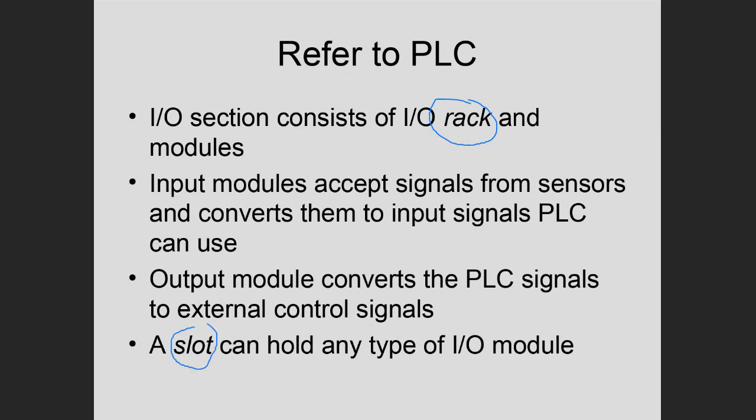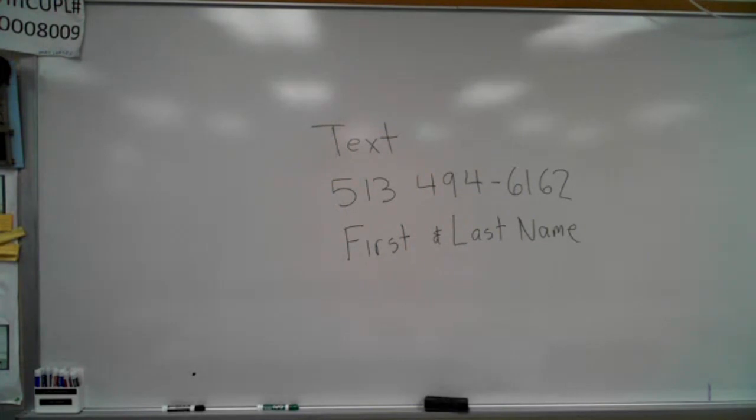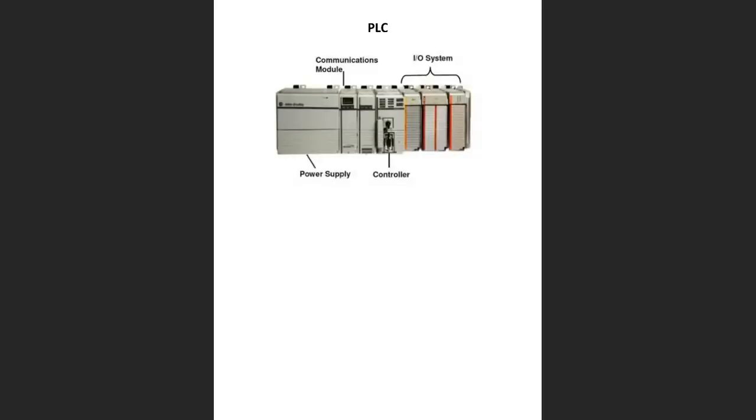Well, if you remember, we mentioned that most PLCs, the larger ones, are modular. So you can get a really small PLC, I say as small as just a little larger than a pack of cigarettes, and that's a unit where you have the power supply, the input, the output connectors all in one unit. But once you go above those small micro PLCs, then you get into the type of PLCs where you have these components or these modules or pieces. So each of these sections you can pull out. And over here we focus on the input output section.